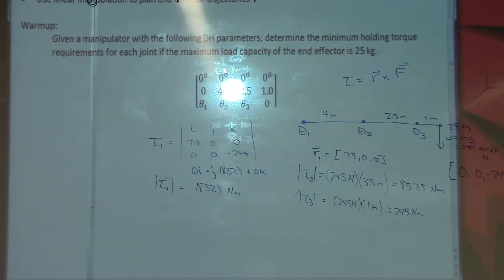If we're selling it to a consumer market, well, consumers are just going to go out and buy a replacement if it dies. So we might just run it with these baseline specifications. For an industrial producer, we'd go with a minimum 25% safety factor. Medical instrumentation and stuff, we'd probably have to shoot this up over 50 or even 75%, because anytime you're working within the medical industry, you're going to have extremely high factors built in to verify repeatability and safe operation of the equipment. So, good.